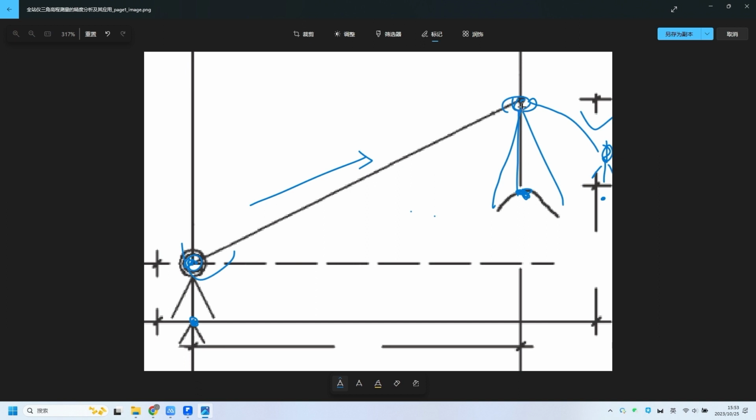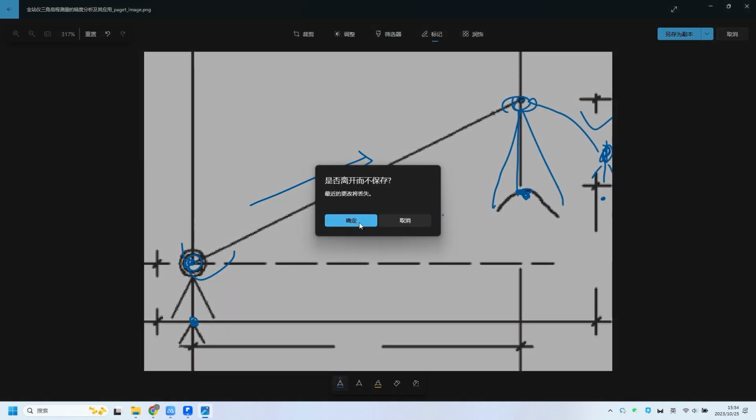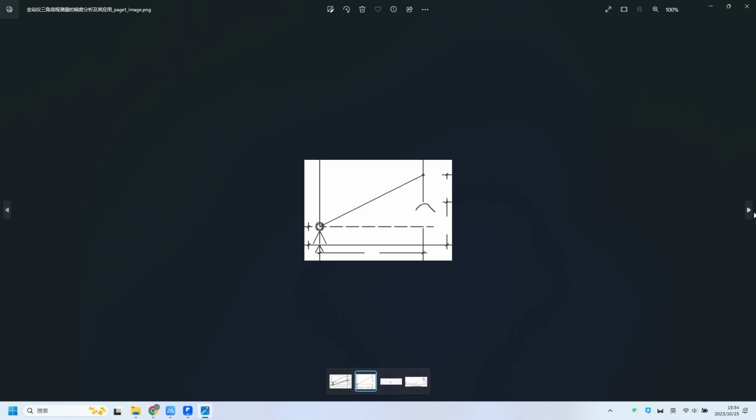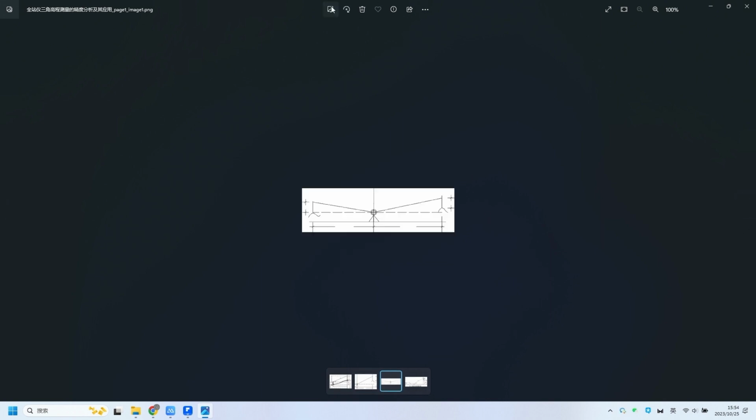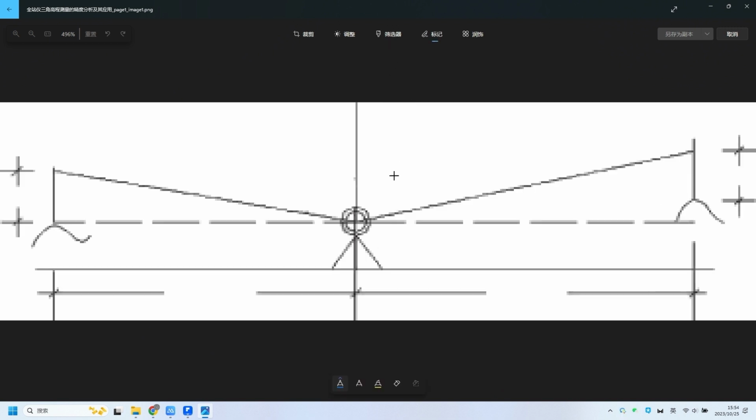If we observe in an opposite direction, we need to set up one observation to observe the height difference between these 2 points, and then set up a second observation, observing the height difference between these 2 points, and then setting up a third observation of the height difference between these 2 points, which is 3 points. It needs to set up 3 observations and 4 height differences. This is our point-by-point setup and station-by-point setup.